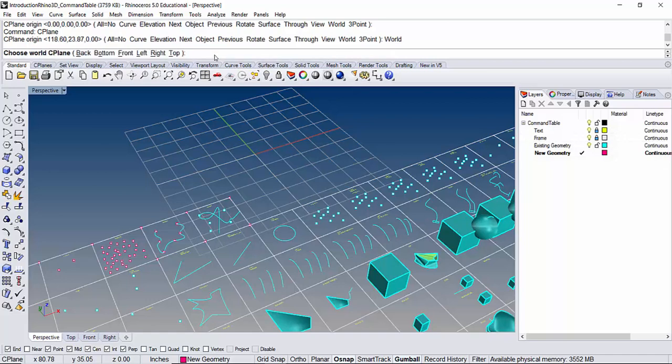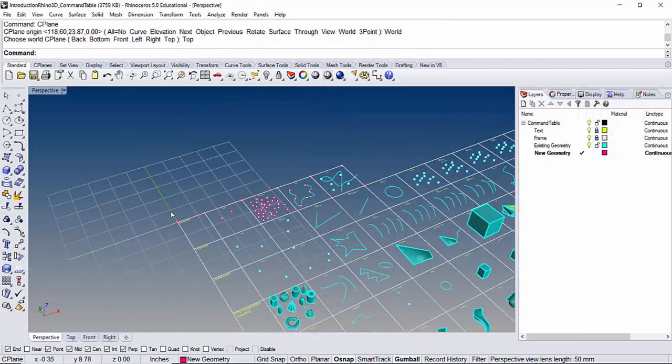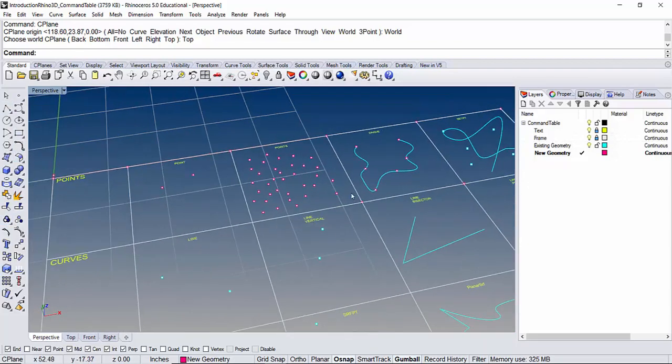So if I select point, then I'm going to say top. So then that moves it there. So world top is the default that Rhino has. But your construction plane could change. So for instance, I want to model something and my object is completely rotated. So you can align it based on the world XY or based on your object. We're going to get into C-planes as we become a little bit more advanced. For now, we're just assuming our world plane is our C-plane. All right, any other questions about points?